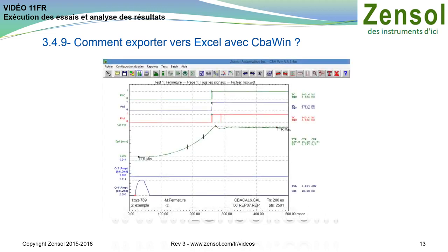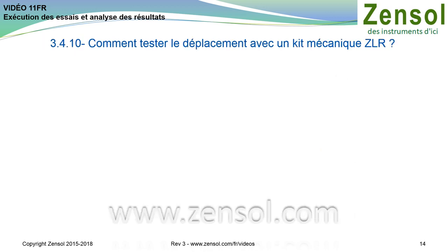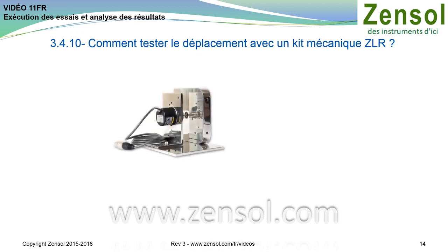Here's an example of what you get on a phase A contact of a rotary circuit breaker. To see all measurements related to contact 1 and its speed, go to page 5 using the red arrows. The speed is shown at the top, followed by the displacement curve, then the contact 1 closing time.